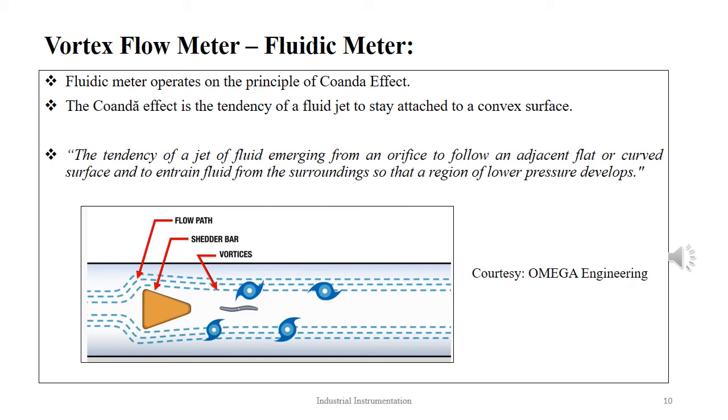The feedback flow intersects the main flow and diverts it to the opposite side wall. The whole feedback operation is then repeated, which results in a continuous self-induced oscillation of the flow between the side walls of the flow meter. The frequency of oscillation is proportional to the volumetric flow rate. The frequency is detected by means of temperature sensors like thermistors and other different types of sensors.